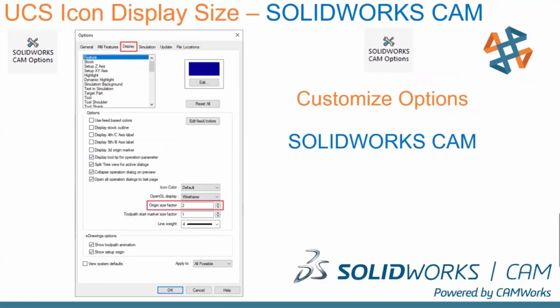The other one is, I hate to admit it, but none of us are getting younger, right? Or everybody's getting older every day. The UCS icon is a nice size as a default, and this is in the CAM side of stuff. Where your UCS icon is, I doubled it. You can make it even bigger, but you can see it comes out as a 1 in your options under display. I double it, so 2. I've seen some people at 2.5 or 3 or whatever, but I like to make that UCS a little bit larger. Kind of sticks out a little bit better.